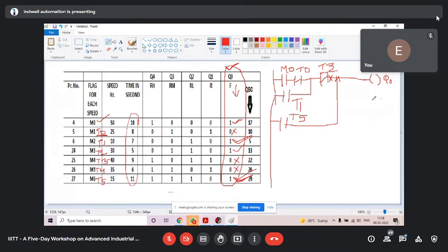But when you design a motor of suppose 400 hertz, then that AC drive will increase that frequency inside it. It's not like it will increase hertz of your home or for all appliances. For that motor, AC drive will do the things inside it, and it will increase that to 400 and give to motor. So it can be increased. It's not like if we have 50 hertz maximum, then it cannot be increased. It can be increased. See, it was increased, then only we have 60 hertz outside. Okay.